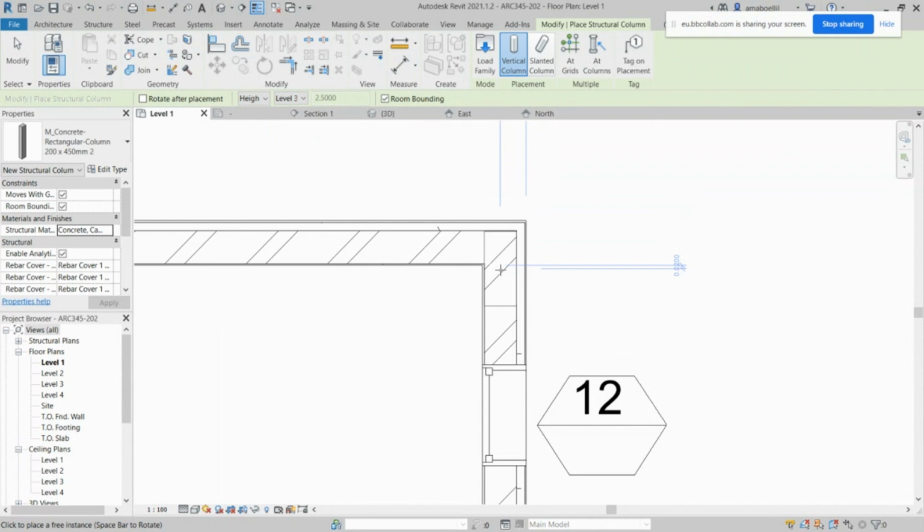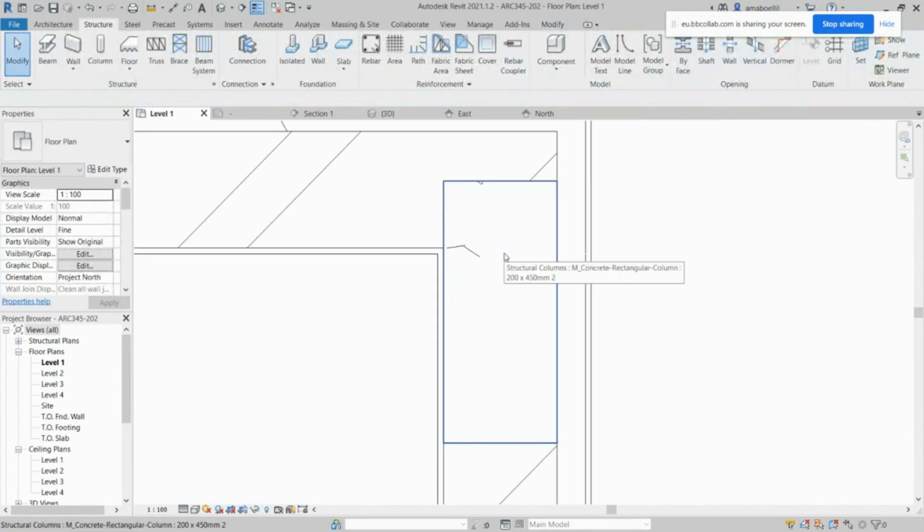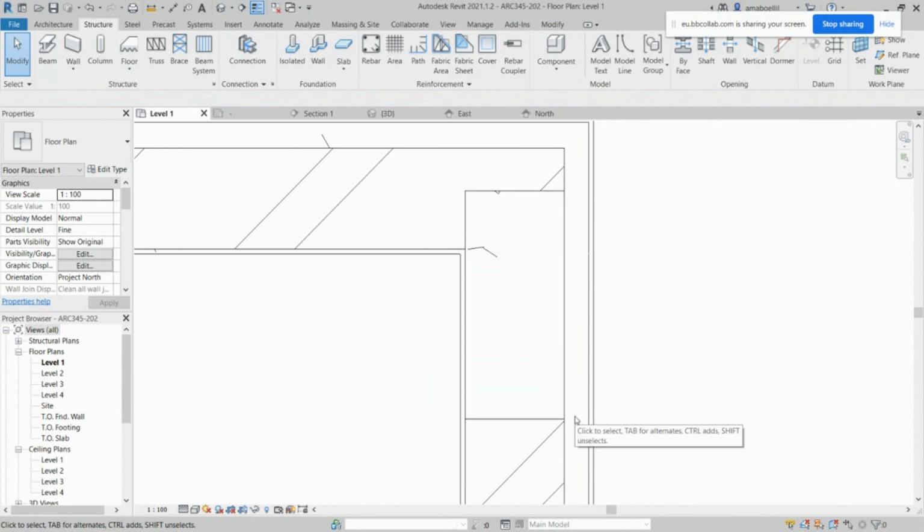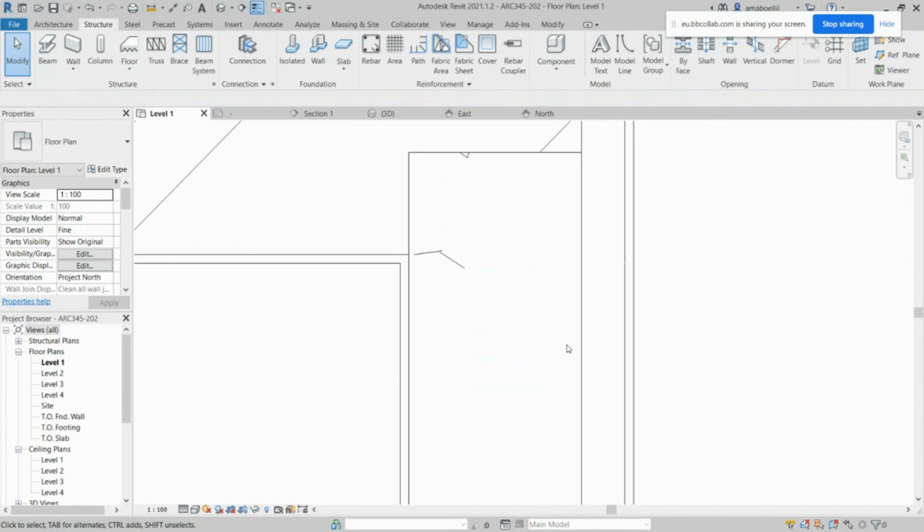This is something also you need to be careful about while you are placing the columns. Sometimes the column is not going to be placed properly, as you would see from here. So this is one of the problems that you would see. So suppose I place it in here. This is my column here, which has several things we need to adjust for. One of the things is that the width of the column is 20 centimeters and the width of the brick is 20 centimeters, which work perfectly together. Sometimes the column might be bigger than the brick in here, and that will cause lots of problems, by the way, because now imagine this wall again.